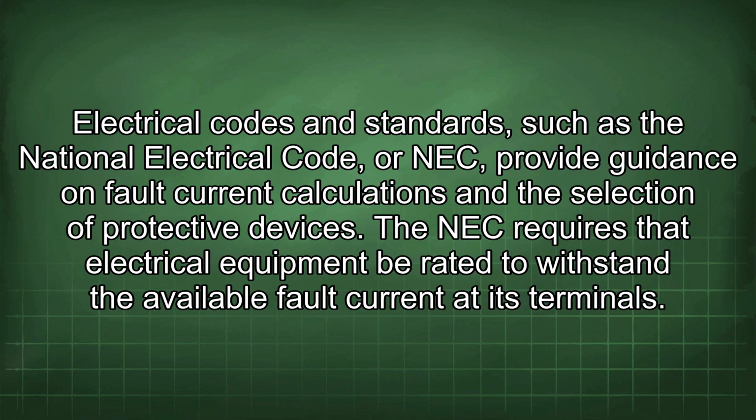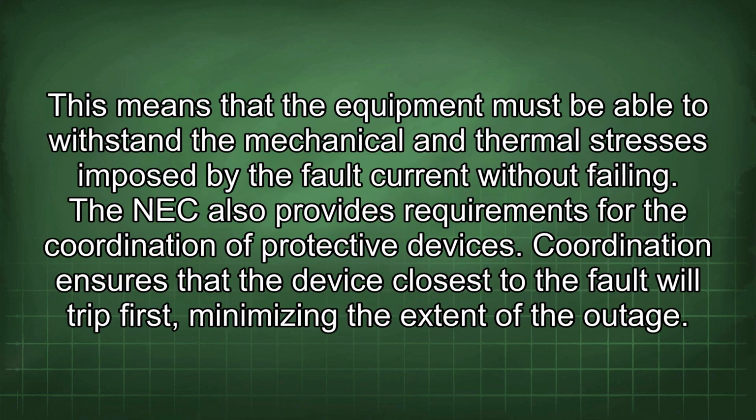The NEC requires that electrical equipment be rated to withstand the available fault current at its terminals. This means that the equipment must be able to withstand the mechanical and thermal stresses imposed by the fault current without failing. The NEC also provides requirements for the coordination of protective devices. Coordination ensures that the device closest to the fault will trip first, minimizing the extent of the outage.